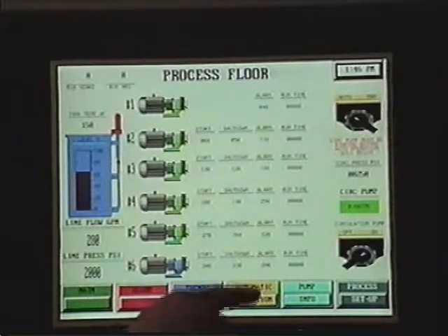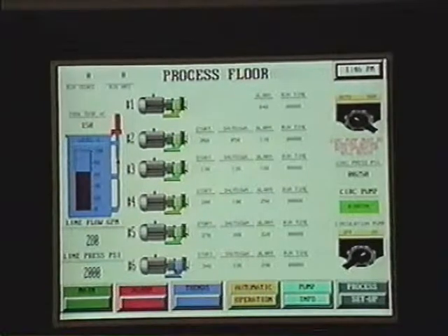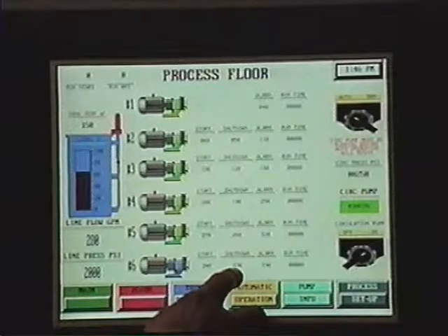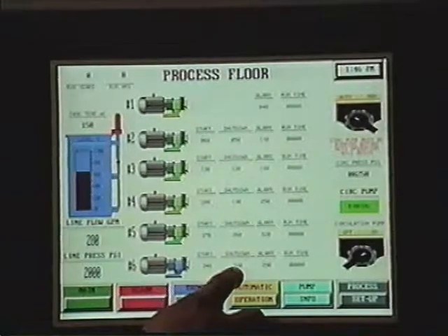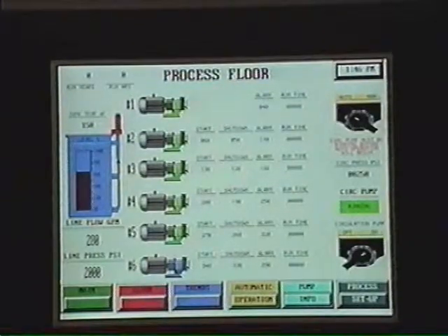At this time, I'd like to point out, you probably saw these things pop up as I was running it. It shows the pump start value. It will start at 340 GPM and shut down at 330, so we'll be in order. And the alarm value is 390 GPM.